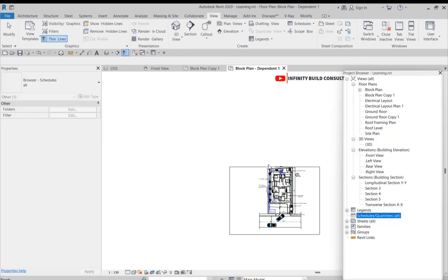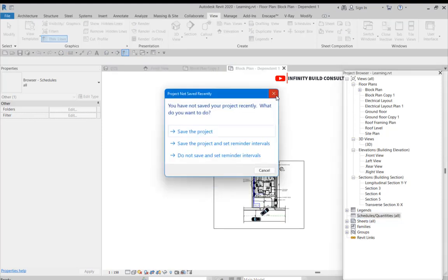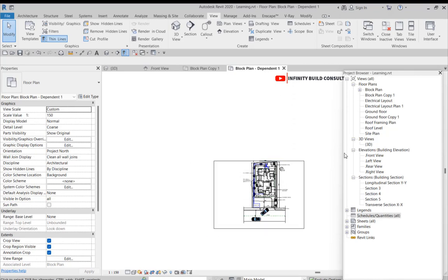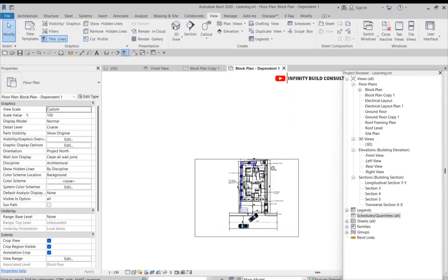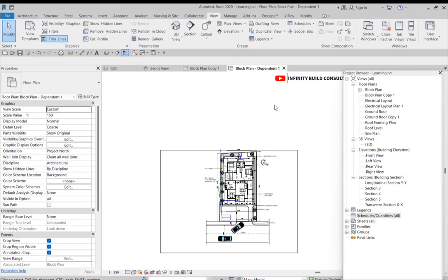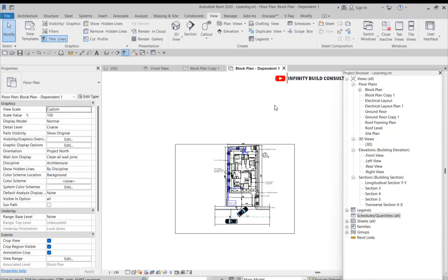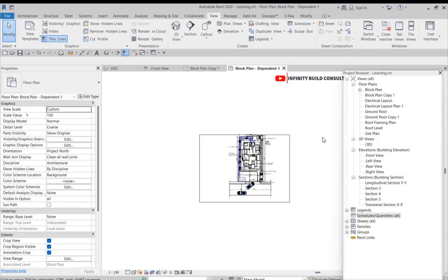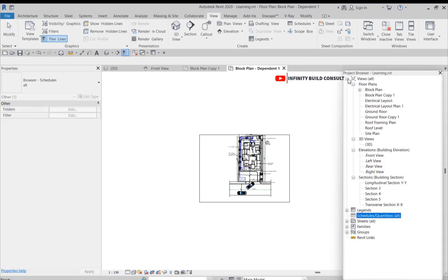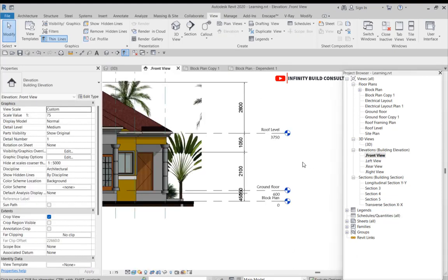In case you are an architect or a structural engineer and you are working, all you have to do first is know the type of building you are creating, whether it's a 2-bedroom or a 3-bedroom self-contained, or a story building. When you open your project template, you just have to come to elevations first. Under the elevation, you just have to create your levels.